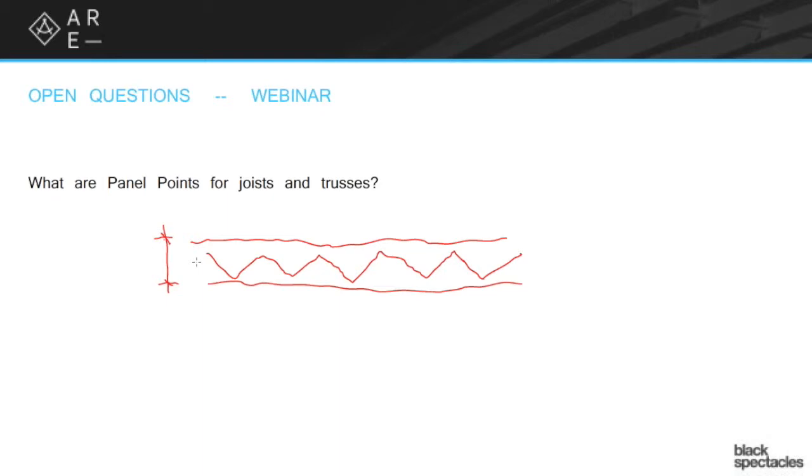And trusses can span anywhere from a floor truss for a wood frame house, made out of 2x4s, where each of the members is a 2x4, and that might span anywhere from, say, 18 feet to 26 feet or 30 feet even, all the way up to really giant steel trusses, or concrete trusses, that can span hundreds of feet. So the truss is very flexible, used in all kinds of different settings. But the gist of it is I'm looking for as much depth as I can get for the amount of material that we're using.